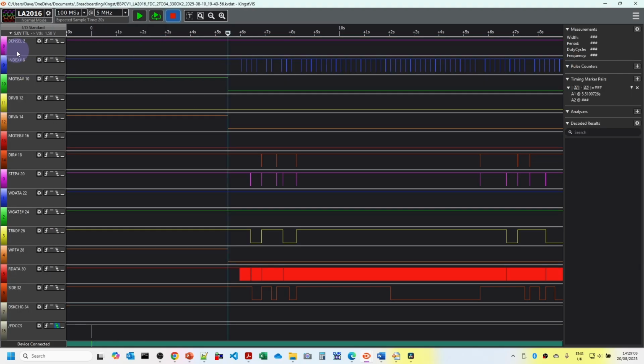This is then the floppy disk signal. So you can see down here I've got the floppy disk cable pin number and the actual signal here. Some of the important ones, things like the index, shows when the floppy disk rotates and there's a hole in the floppy disk. So you should see this give a signal about 5 times a second. And the track 0 indicator indicates when the floppy disk is on the outer track, or track 0. And then the read data is the MFM encoded data, so we can't really make much sense of that using this logic analyzer.